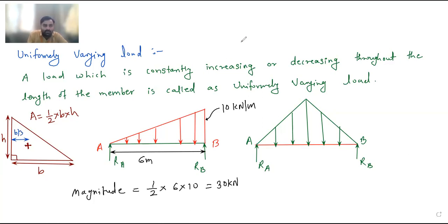And now if you see the vertical distance, again from the right angle, here is the right angle. This total height is H. So from the right angle, it is again 1/3. So this will be H by 3. So this is the point where the CG of the right angle triangle is situated: B by 3 and H by 3 from the right angle.